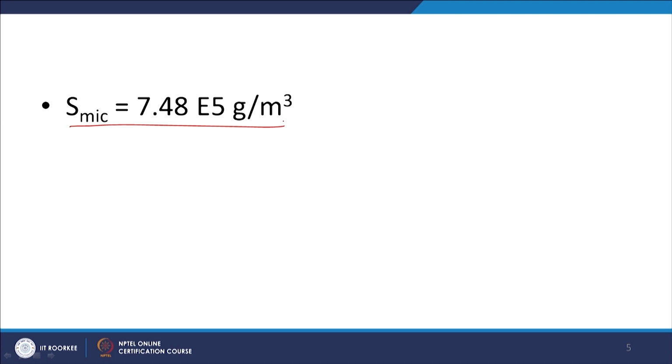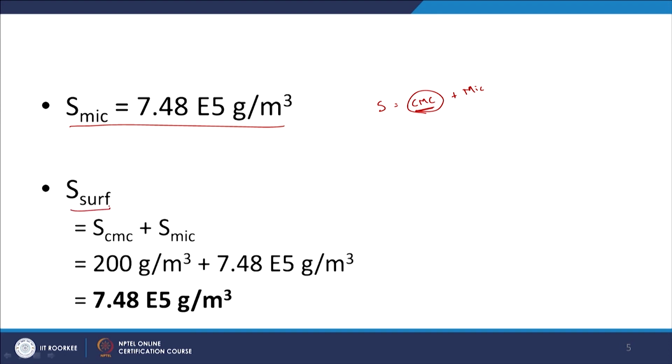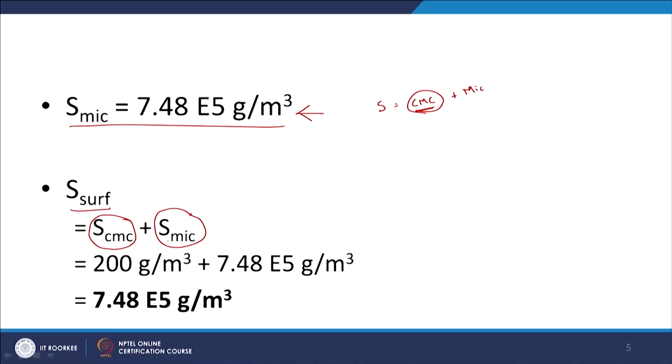So, that is something we are going to have, and based on that particular aspect, I end up calculating this as micelle, but the total surfactant will be the one present in both the critical micelle concentration, because this is how much I need to add before the micelle is formed, and the one in the form of the micelle, right. So, let us look at what we have out here. The total surfactant that I need to add is based on the amount of surfactant that I need to initially add before the micelle is formed, and again the amount of micelle required. How did we calculate this? We calculate this particular variable based on the amount of surfactant needed to completely dissolve a particular amount of NAPL, for a particular volume of water, or the surfactant.